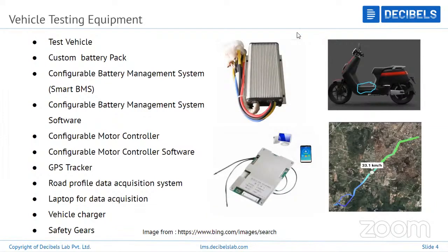Yeah, correct. Another doubt attached to that grade. I think it was covered in yesterday's session, but I'm asking now. When we are having a negative gradient like a downhill section, those cases won't be considered while powertrain sizing, right? We will be considering the extreme side of that gradient. That's what I said, while testing the discharge current was different when you compare it with BMS data from the powertrain module. Again, as you said, when you are going downhill, if your vehicle has a regenerative property, we can collect data such as the amount of regeneration, what percentage of regeneration was achieved at that certain downgrade. Okay, understood. Thank you.